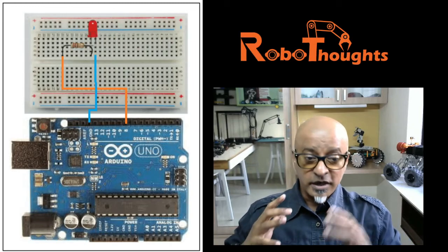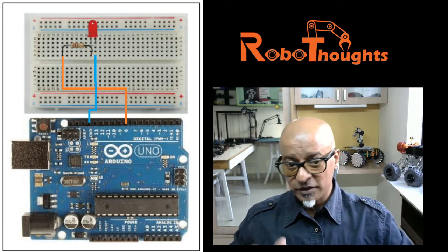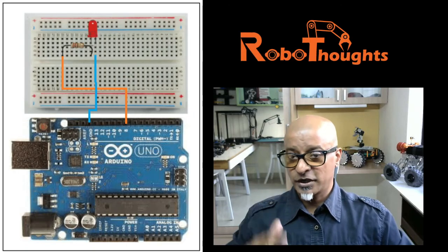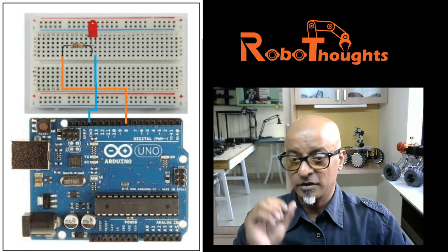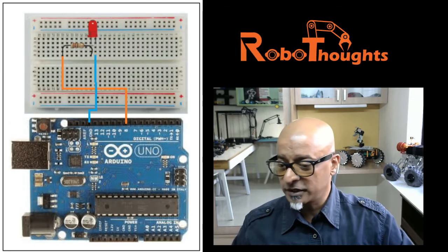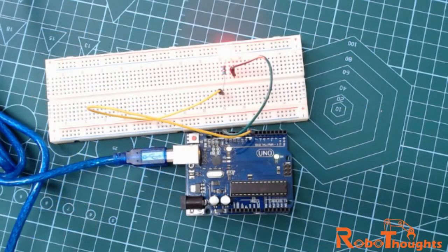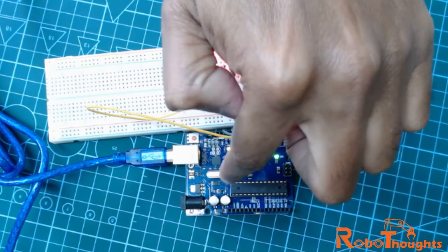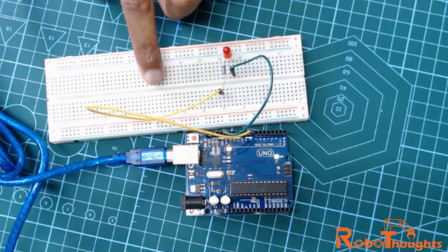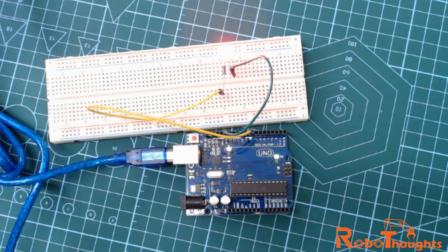Right now, get hands-on with the digitalWrite function using this program which I showed you, and also this circuit, which is very basic and very easy to build. As you can see, it's just 2 wires, 1 LED, 1 resistor connected to your Arduino pin number 8, using a breadboard. So that's how it is, guys.